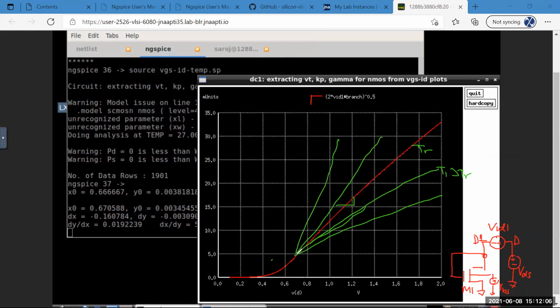And we predicted the subthreshold current. We introduced subthreshold current in the morning. You remember it was like a BJT effect because of the minority carriers, and at high temperature the minority carriers actually increase. So those currents will increase, not drawn to scale here.